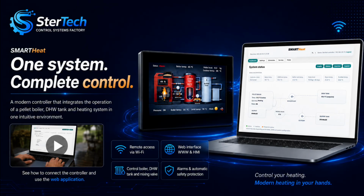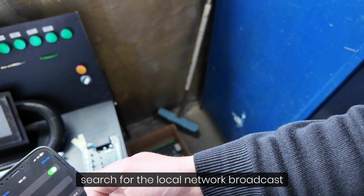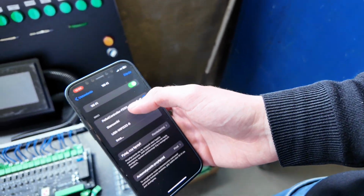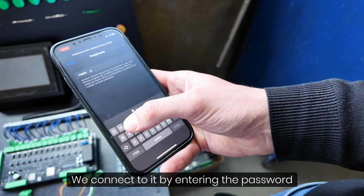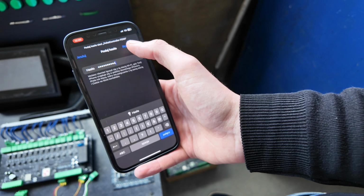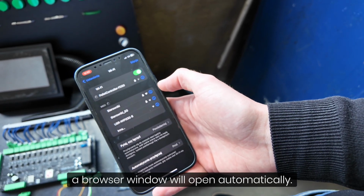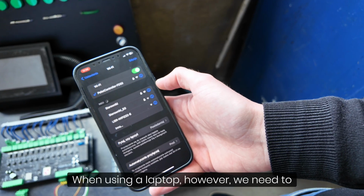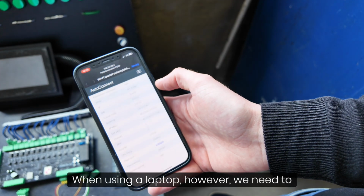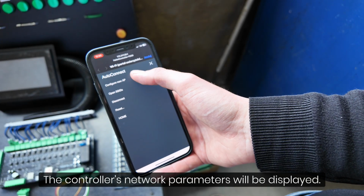To do this, we turn on the controller and, using a Wi-Fi enabled device, such as a phone, tablet, or laptop, search for the local network broadcast by the controller. We connect to it by entering the password provided in the controller's manual. Once we have successfully connected to the controller, a browser window will open automatically. When using a laptop, however, we need to open the browser ourselves. The controller's network parameters will be displayed.